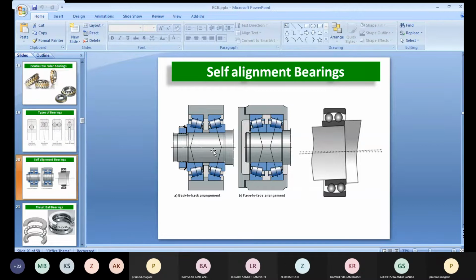Due to that vibration, if I use a roller contact ball bearing, there might be chances of misplacement or changing the angle of balls in the races. So due to that, failure will occur. But here, in the case of back-to-back and face-to-face alignment, this can be made in such a way that it will adjust the load as per the displacement of the shaft.